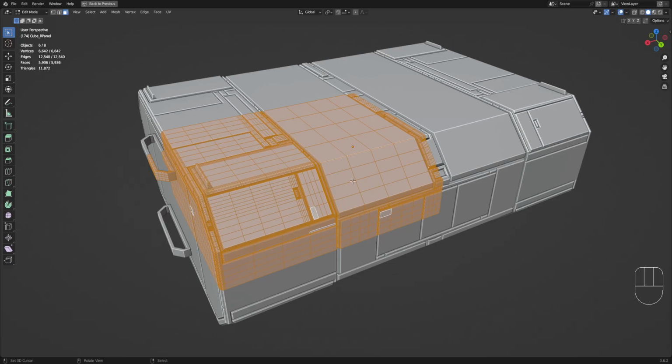If you have a higher resolution and a really complicated shader which uses procedural shading, with a lot of nodes, especially math nodes, it can take Blender a long time to process that shader. You couple it along with a model that has high resolution, then that model is going to slow down the viewport, or slow down the render times when you're finally rendering the scene.